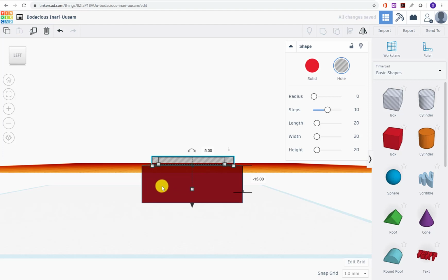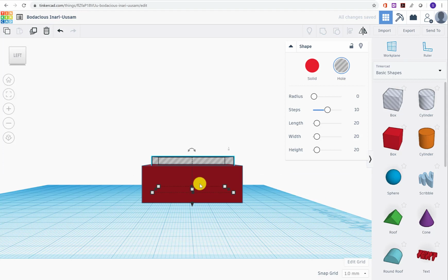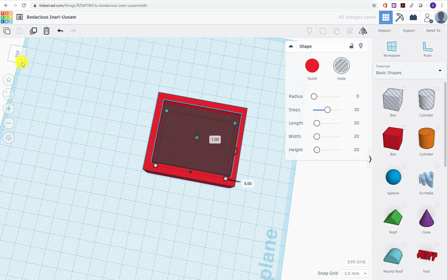But also, if I change the position of my work plane, so now I'm going to grab the work plane and bring it back to my original surface. If I start to bring that down, that number is now relative to this bottom part, and I can say it's 4 millimeters above, I want it 5, so I can move it. Now, if you think about it in terms of a maths lesson, it's that visual spatial understanding of how things work in a 3D environment as opposed to a 2D, and sometimes 2D is really hard to translate.